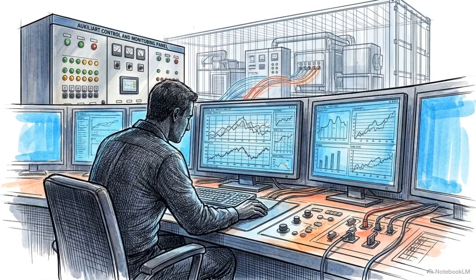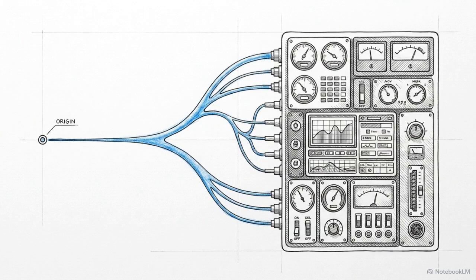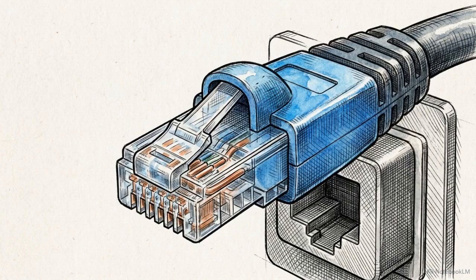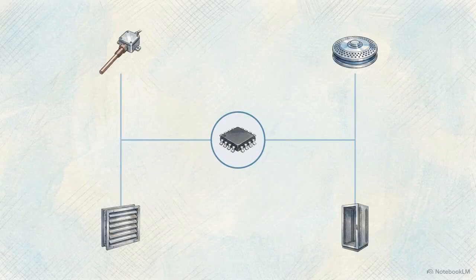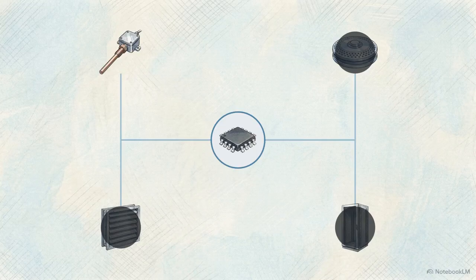When investigating faults, operators apply symptom-to-root logic, tracing the physical path of power and data backward from the digital alarm to its exact origin. Consider an isolated failure. If a single analog sensor drops offline, the technician targets that specific input loop for field inspection. However, if multiple unrelated field devices vanish from the interface simultaneously, the system is experiencing a cascading failure.